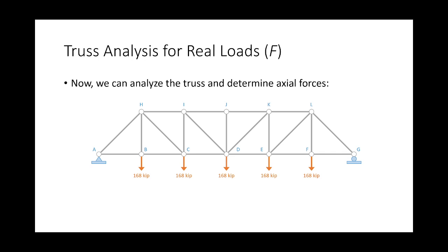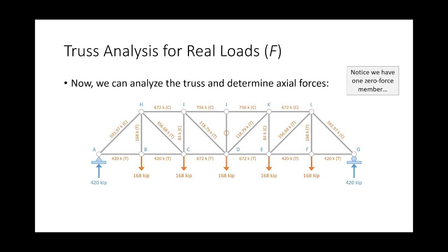Now that's something you can do, right? Everybody in here should be able to analyze this truss. So here's the truss. Determine your reactions. Boom, analyze it. Do I need to walk through that? You can do that, right? I'm not saying we need to go through this step by step. You get the idea. Notice how one of the members is a zero force member. I'm going to talk about that here in a bit. In your truss layout, I would try and avoid those, and I'll explain why. But everybody with me so far?